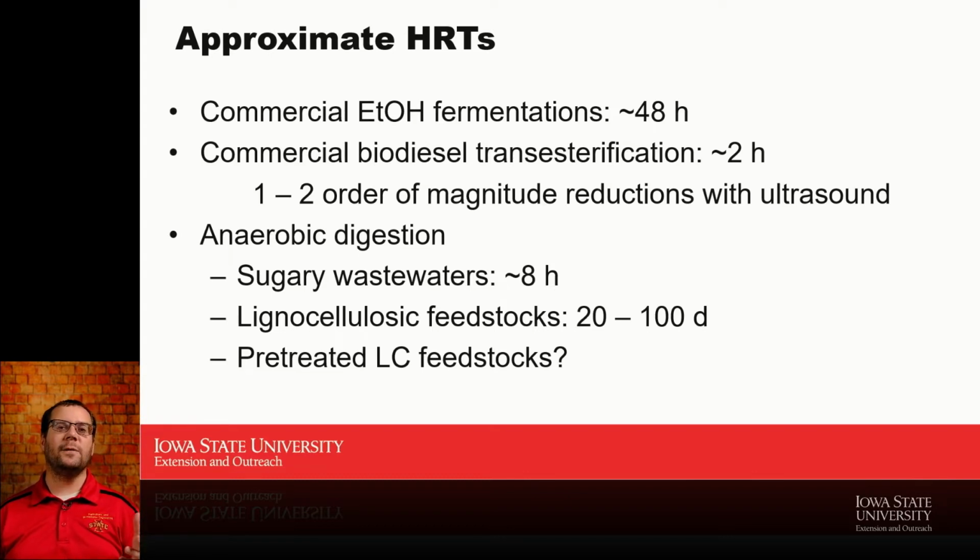So that ethanol fermentation, that's what I have there on the top. We've optimized that to be a relatively fast process, somewhere in the neighborhood of 48 hours. If you think about making renewable diesel, right? So transesterification for biodiesel, that's about a 2-hour process, and you can shorten it a little more with ultrasound treatment of whatever we're turning into that biodiesel. On the other hand, when we move to anaerobic digestion with sugary wastewater, if I'm separating my hydraulic and solids retention time, I might be able to get that process done in 8 hours.